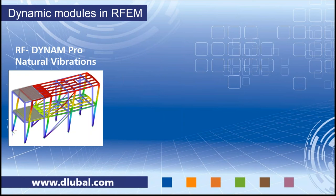So the basic module is the natural vibration module. This is what you always need, and it performs an analysis of frequency and mode shapes for members, surfaces and solid models. You can directly import masses from load cases. You can build combination of masses in so-called mass combinations, and you can import stiffness modifications, axial forces, failing or deactivated members, or stiffnesses from RF-CONCRETE as initial conditions. So these are just a few examples. We have 4 eigenvalue solvers available, which I explain more in detail when we go through the example.